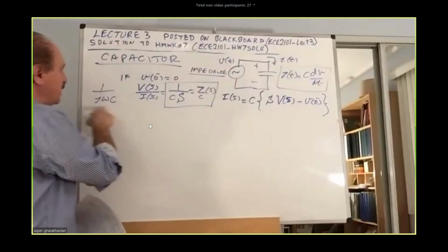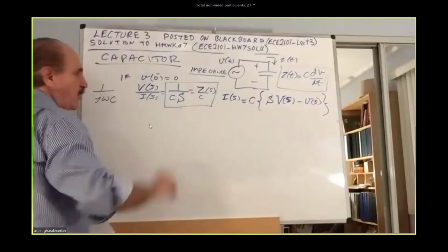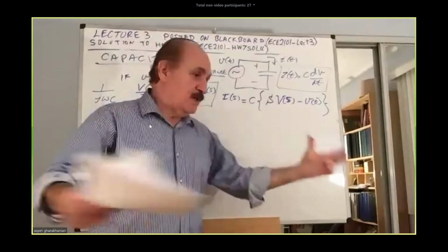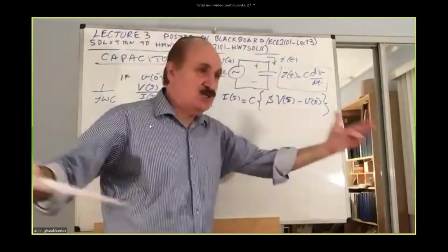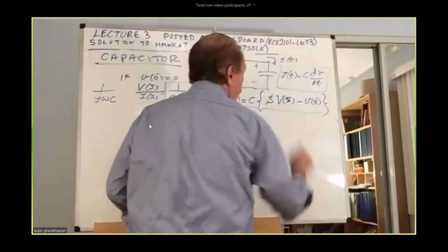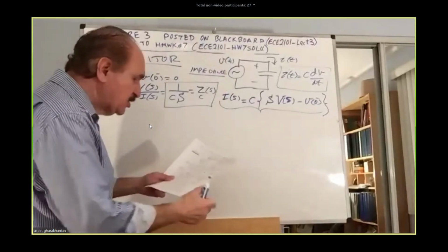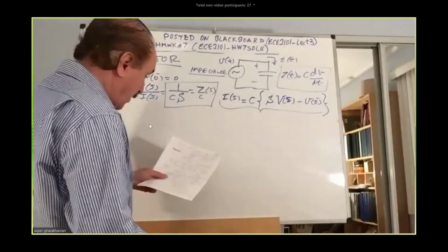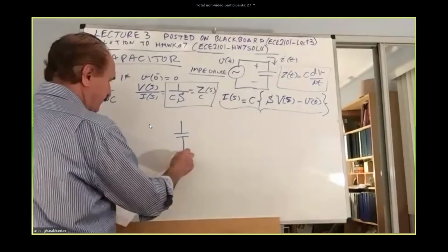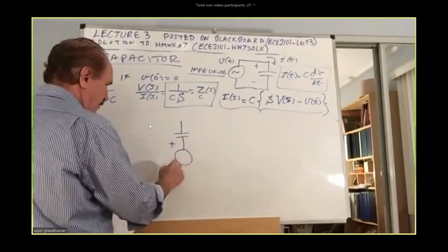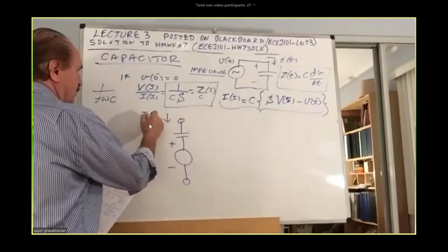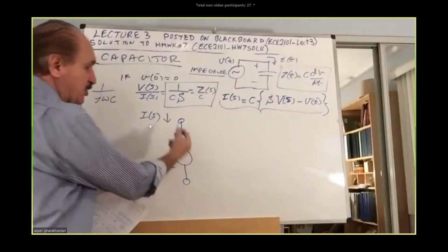Impedance has a meaning if the initial condition is 0, because you can get the ratio. However, if the initial condition is not 0 and you're solving a circuit that possesses initial energies here and there, then we need to model that equation, just like before. So these are the standard models of the capacitor. Here, you have C, a voltage source. Then you have I of s, that's the Laplace of current, the series current, and that's the series model.